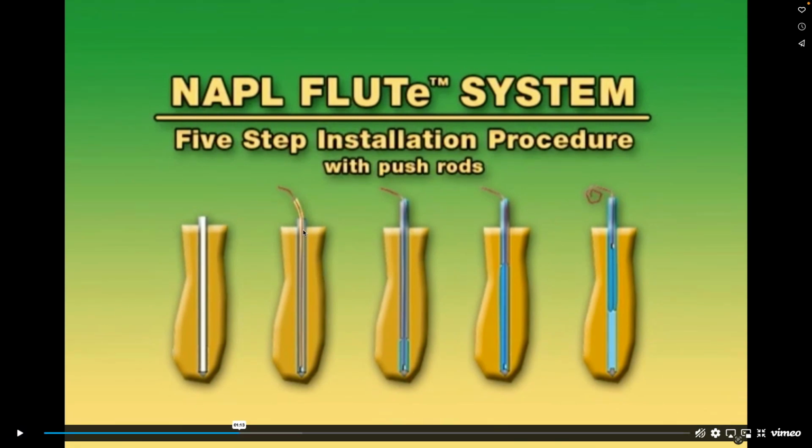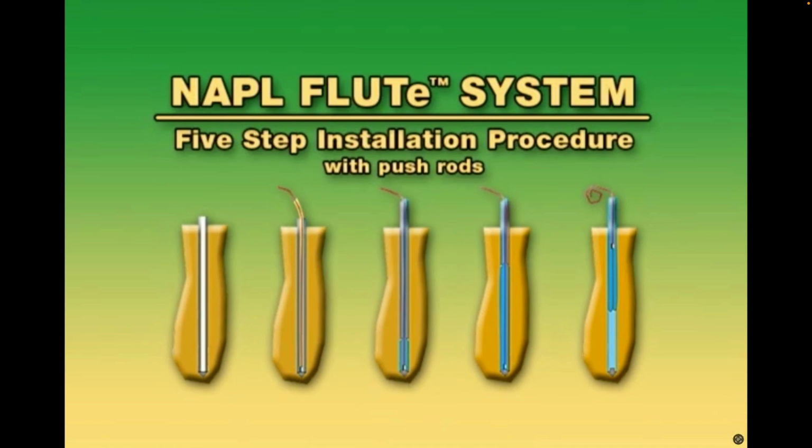You drill a borehole, you put down a composite tube on the outside, but with the cloth on the inside down to the bottom. You retract the covering sheath around the fabric up to the surface, and then it sees whatever is in the aquifer around it, and then you pull out the whole fabric sheath and you measure what's there.